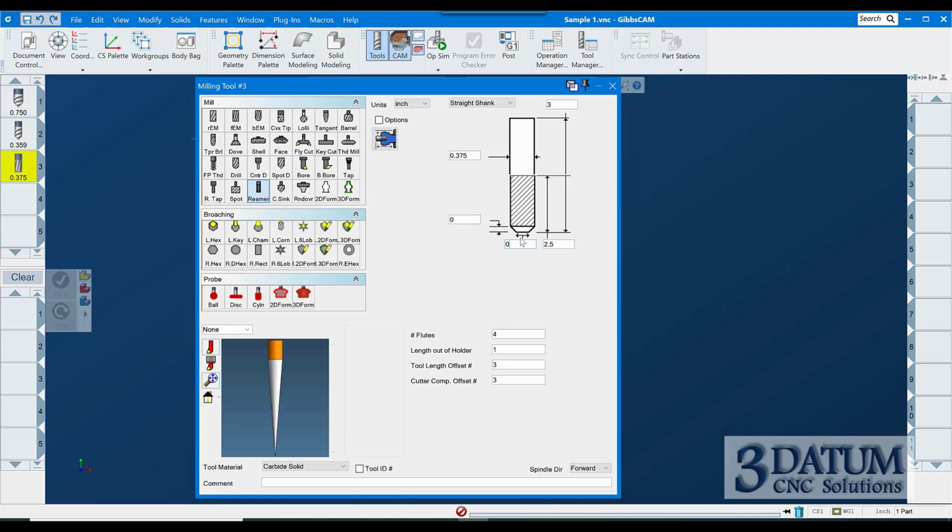I have told people before to zero that out, but the problem with that is if there's no chamfer, it shows that going from this diameter at the top of the flute to this diameter at the bottom of the flute. To me, this is a bug. I've reported it, but anyway, if you get these numbers probably correct, then it looks right.